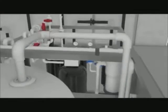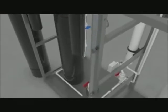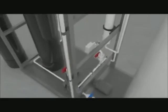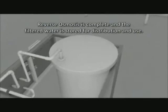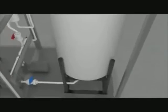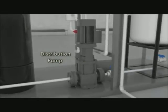At higher salt levels, the concentrate is sent to sanitary sewer, or in some cases non-critical locations for reuse, also known as gray water recycle. In higher water recovery applications, a small percentage of the concentrate water is sent back to the inlet of the RO membrane for recycle. The salt removal reverse osmosis step is complete and the filtered water is stored for distribution and use. The product water is fed from the bottom of the tank to the distribution pump, where it will be post-treated before being fed to the facility points of use.